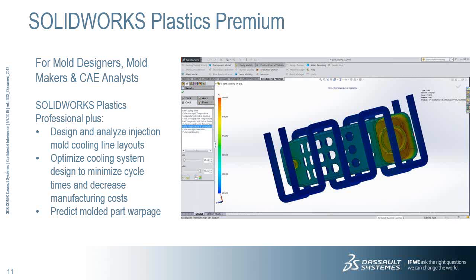And also for the bigger parts, which are more in length and width, it is always known that you will have warpage. Warpage is the bending of the part on one side, pulling the part to one side, because of various reasons like material strength or material properties, mechanical properties, and so on.